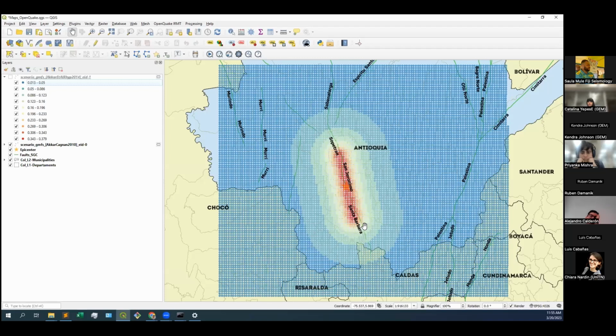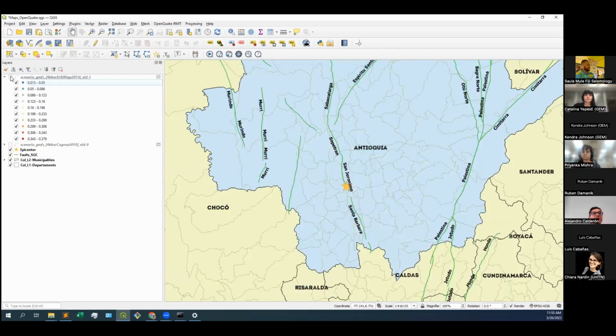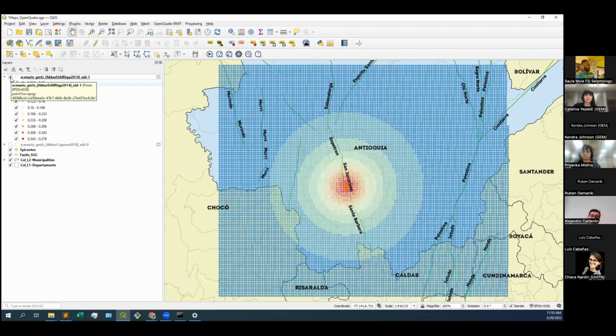whereas for the other there is high ground shaking along the fault trace, following that strike of 348 degrees, because this GMPE uses my closest distance to the source, not to the hypocenter, but to the projection of the fault on the surface. So what I want you to know is that there are huge differences between GMPEs. Each GMPE, because of the parameters it uses, will give you very different predictions of ground shaking.